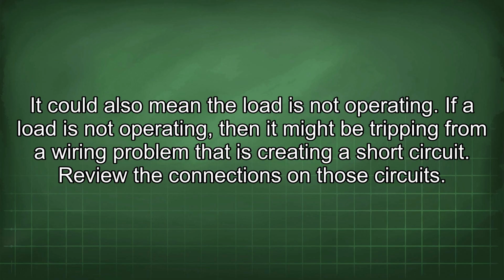If a load is not operating, then it might be tripping from a wiring problem that is creating a short circuit. Review the connections on those circuits.